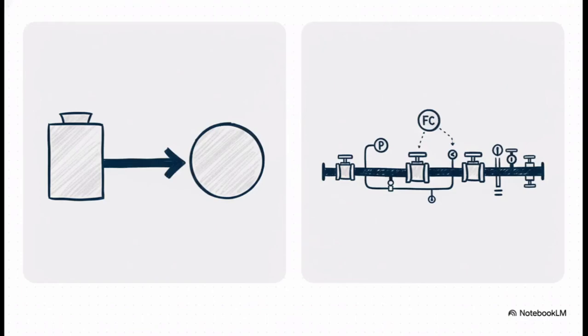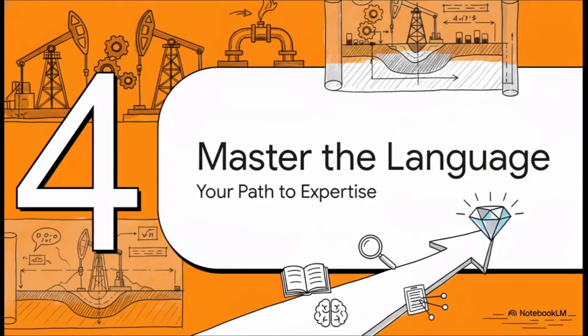On the left, the PFD is the strategic big picture. It shows how the major pieces connect and how the flow evolves. But the P&ID on the right is the technical plan that gets into every single detail in your plant: pipe, valve, instrument, equipment. It's the difference between knowing a final destination and having detailed turn-by-turn directions to get there.